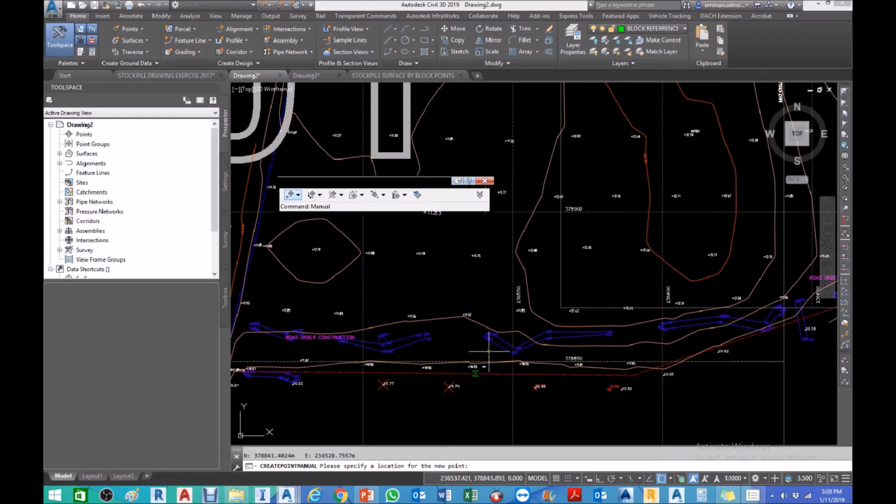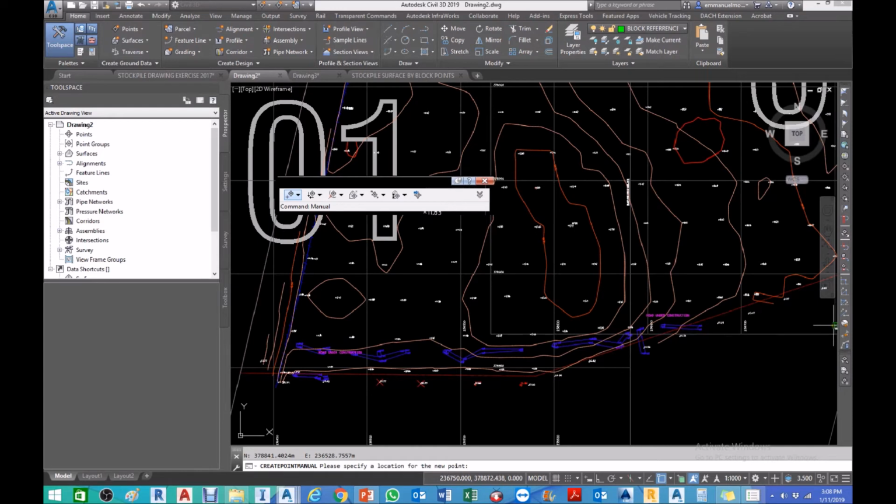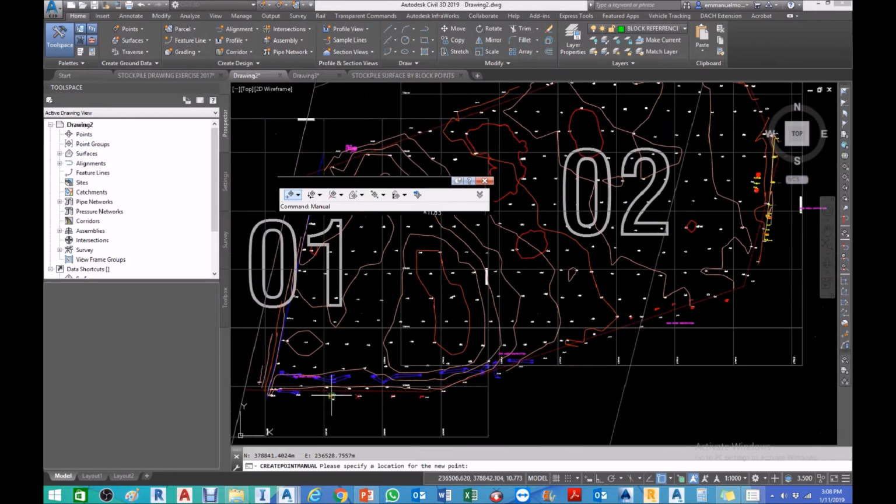Also we know that there is an option in Civil 3D that we can draw a polyline, but only if the boundary is in sequence. Okay, so on the site, this one is a very big area, they need to specify the boundary in the coding. If not, it's not a mistake, but it will really take time for you to process it.